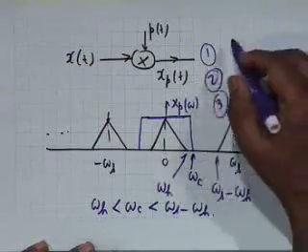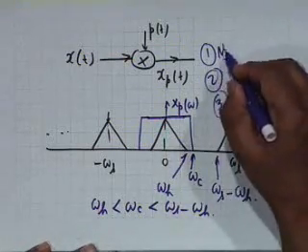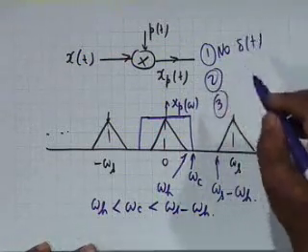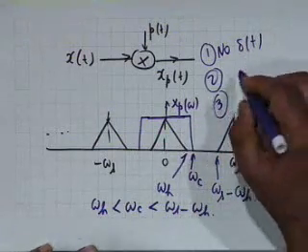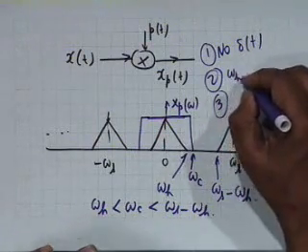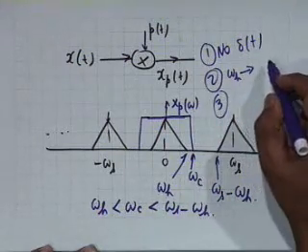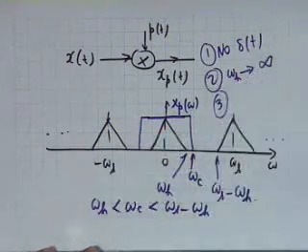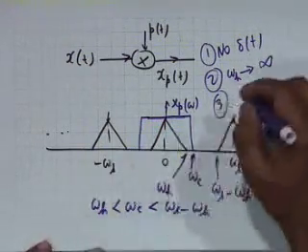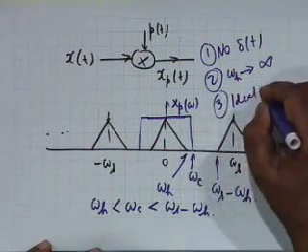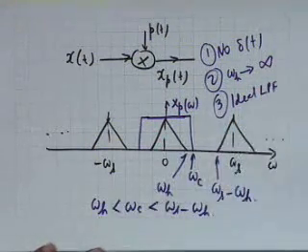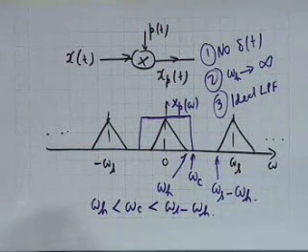First, no delta function can be realized in the laboratory. Number two, omega h in practical signals tends to infinity. There is no band limited signal. And the third is, an ideal LPF cannot be realized. And therefore, in practice you shall have distortion.